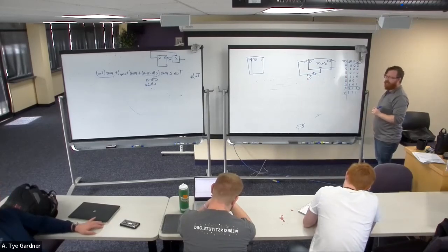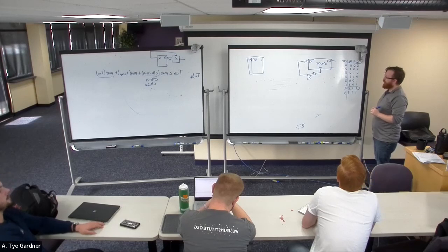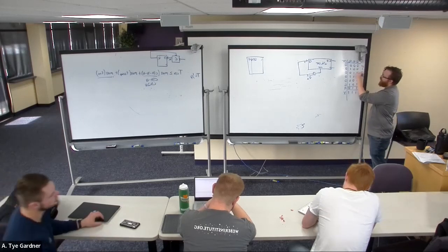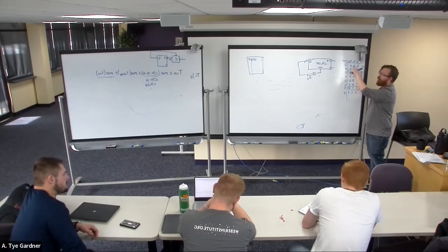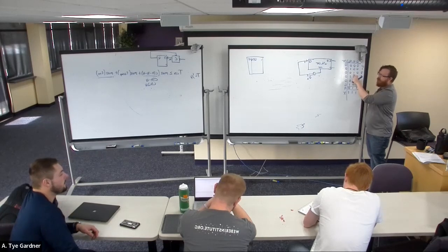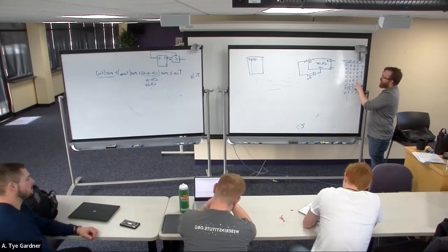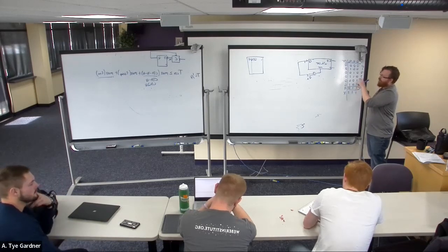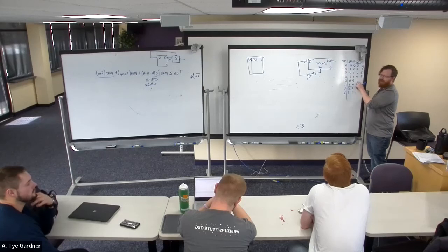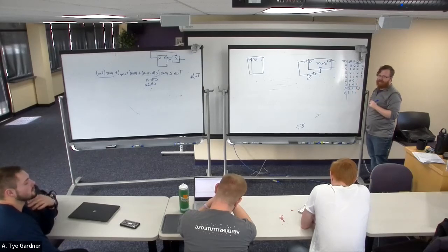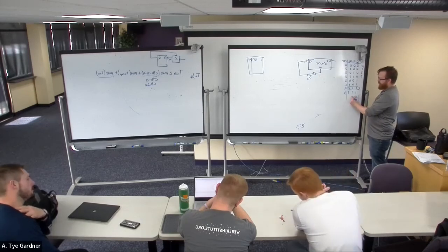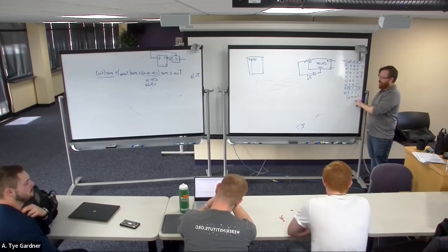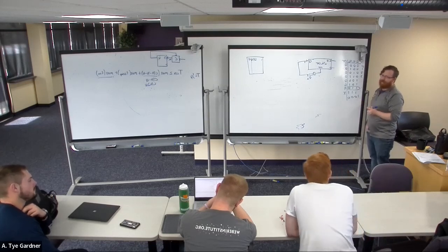So if you only wanted to count to 3, then you could just say, connect your reset right to Q2. Yes, exactly. If we only wanted to count to 1, we wanted to go 0, 1, 0, 1, we'll reset as soon as here. No, if you want to count to 3, then you connect it to Q2. Oh, to Q2, yes. If I only want to count to 3 and I want to reset here, then it would just be a Q3 feedback to the reset. So if you wanted a simple reset on a counter that would count to 8, then you could just add a Q4 and reset as soon as it was 1. Yep. If you had a 4-bit counter and you needed a 3-bit counter, that's what you would do.